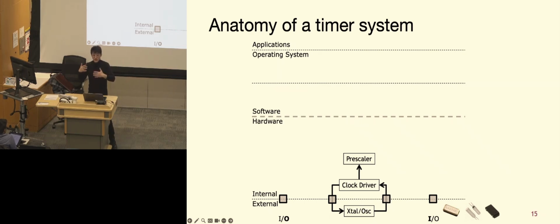But in terms of most of the programs, most of the interactions we want to deal with at a human interaction frequency or at an embedded system handling speed, chances are the clock is pretty fast, and we don't really need all those cycles triggering the peripheral devices. So we have this prescaler that basically divides the clock frequency to achieve longer time intervals. For example, if the system runs at say 40 megahertz, with some prescalers we can scale it down to 4 megahertz or 1 megahertz for some specific peripheral devices on board.